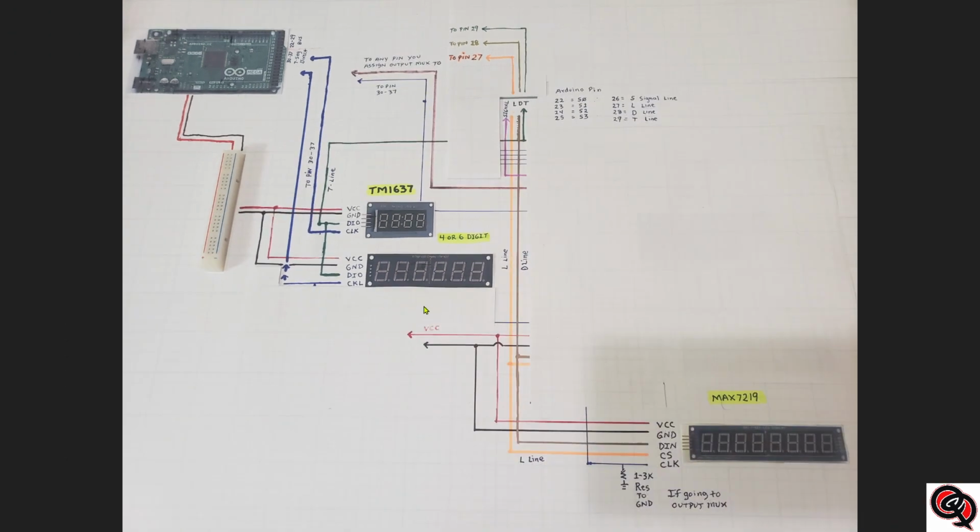But anyway, after you have your voltage and your grounds connected to your displays, you can join all the grounds and all the voltage ones together, like I've said before. So even if you have 5 displays, you can daisy chain all the grounds and then just take one of them to the main ground, or you can daisy chain all your voltage lines and then take one of them to the power rail. And it doesn't matter what kind of display it is.